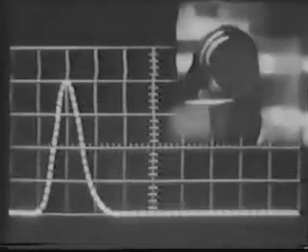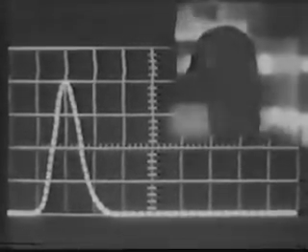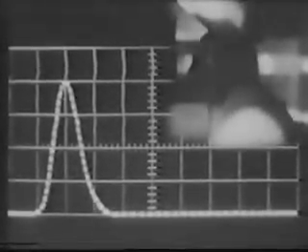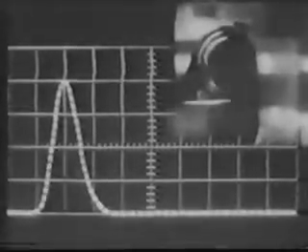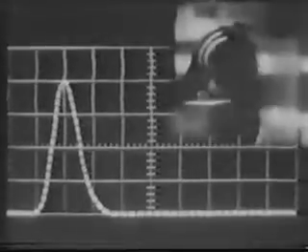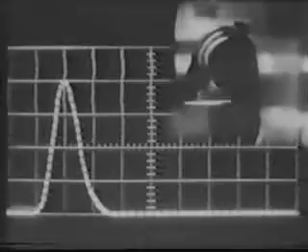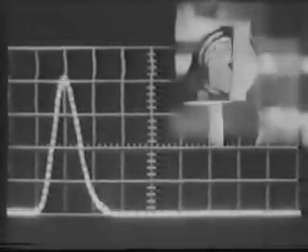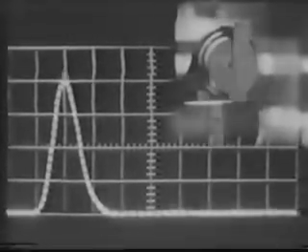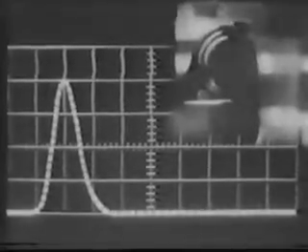Now I'll cut the light intensity in half by covering one of these two holes through which the light passes. The resulting pulse height has fallen to 2 units, but I can raise it to 4 units again by doubling the gain of the oscilloscope. Now you can see that the hole pulses that are 4 units high coincide at all points with the pulse for full light intensity. This coincidence of the pulses shows that the oscilloscope deflection is proportional to the hole concentration under the detector.